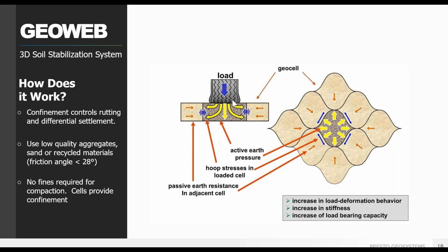given load. One of the advantages of geocells is that we can use the low quality friction angle materials: coarse sands, recycled materials, recycled concrete, sandy aggregate mixtures, basically the 20-degree friction angle materials. It does really give us a benefit because, the lower the friction angle to a point, the faster we get that vertical load engaging with that cell wall. So like I said, you'll probably hear that many times through the presentation today, but that is a very important part of a geocell when you're comparing it to other geosynthetics, such as the grids and textiles that really do require high quality, high friction angle infill materials.